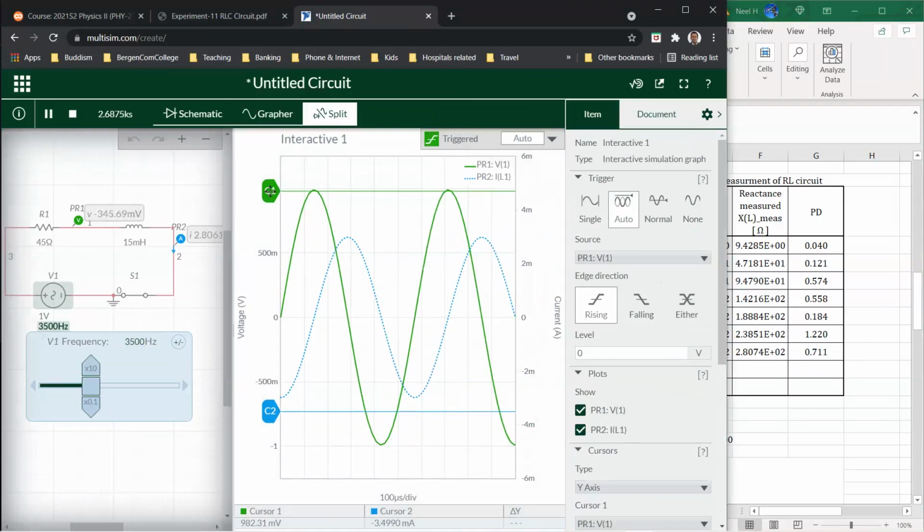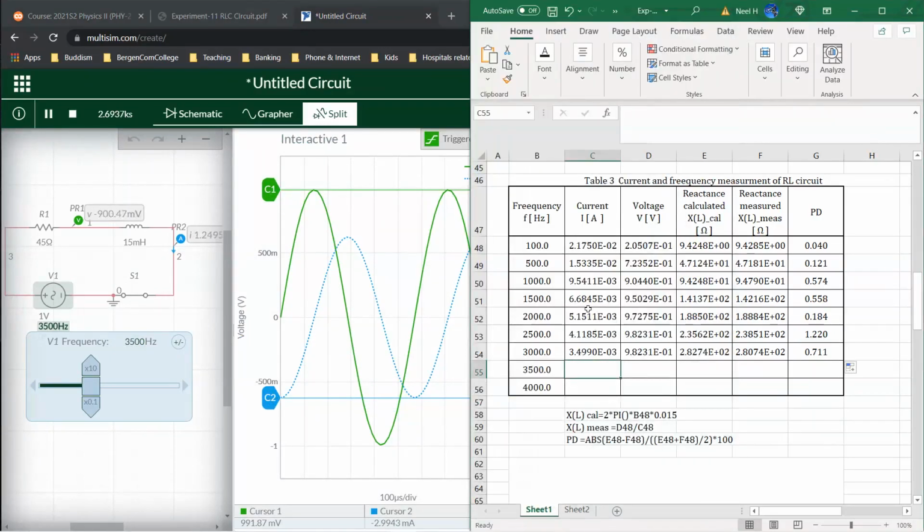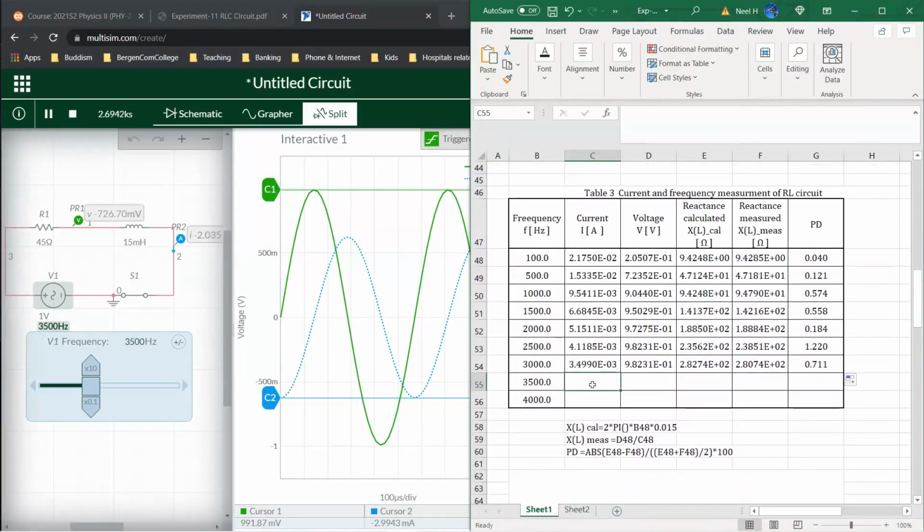Voltage seems to remain steady at higher frequency values. Voltage is not affected much, but the current is affected. Those are the observations. If you do a lab report, those are the ones you have to discuss in detail: what you really observe by doing exactly the same frequency range relative to the capacitor. What changes happen? What's the observation? Since we're not doing any lab report, that should be fine, but those are the things you have to pay attention to.